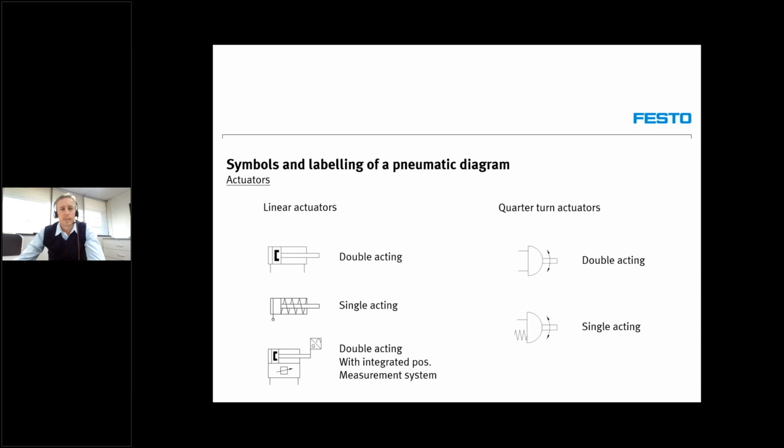Hannes, if I may come in here. Yes, Rolf, please. I'm going back many years where one of the major steel plants actually wanted to order another compressor from me. And I supplied a compressor just to get a call. While they're going to have a meeting, I requested we do a plant walk-through. And your leakages you can detect very much by normal ear because of the pressure. And by the time we finished the survey, I said to the gentleman, please fix all your air leaks. I don't think you need another compressor.